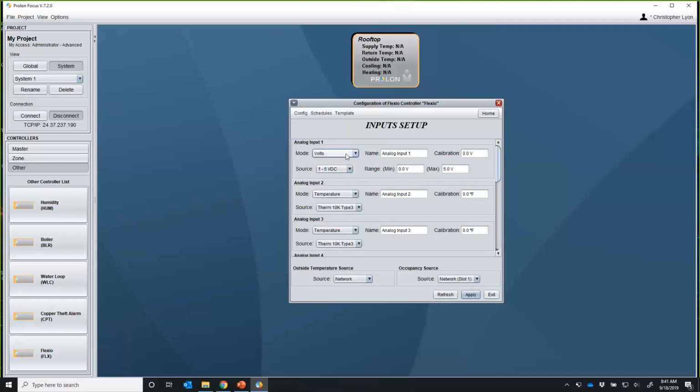You're not landing high voltage to the controller. Current, amps, milliamps, frequency, so you can get feedback out of VFDs with this. Kilowatts, flows in CFM, GPM, liters a second, velocity, speed, level.